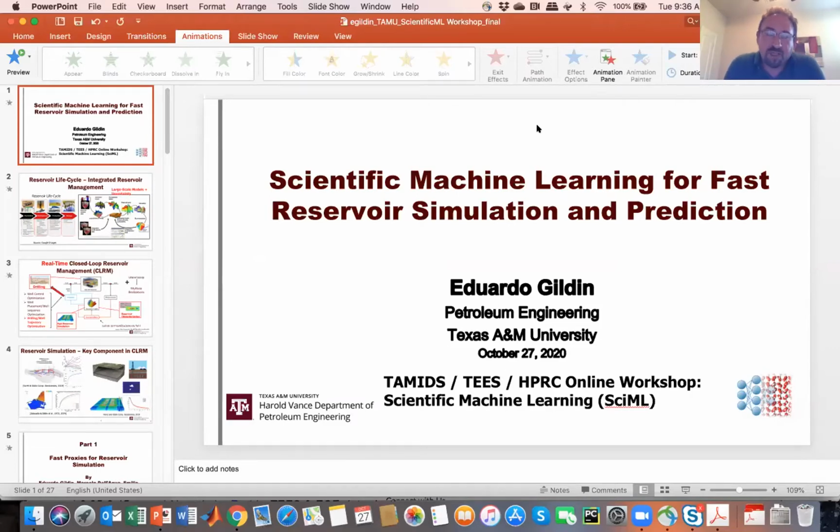And if you just look at POD, which basically you just do an SVD of the states, you are guaranteed... I mean, this is much more robust, right? You may play with a little bit of how many POD bases you want to have, but in the end, yes, it's very insensitive to whatever you do to the system, right? But eventually, we want to come up with an architecture that doesn't translate into states.